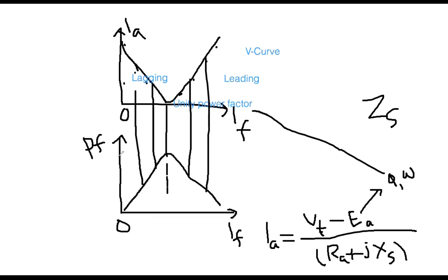That's why this is your power factor 1 position, and then gradually, for example, this is just an example, 0.2, this is 0.6, this point is 0.8, and then finally here it is 1 power factor at this point. So again, from this point, your left side is lagging power factor, right side is leading power factor.